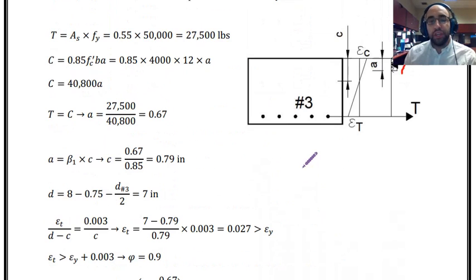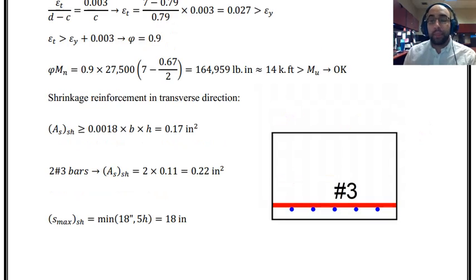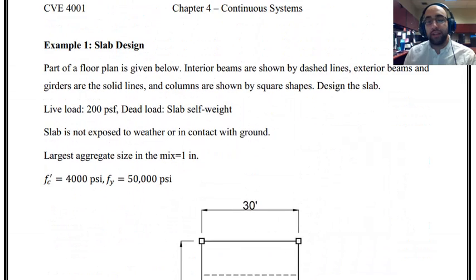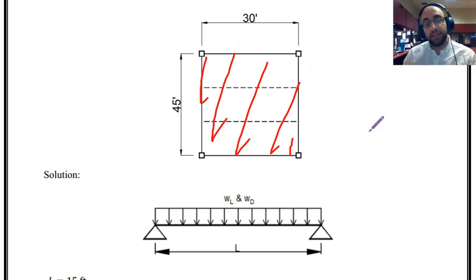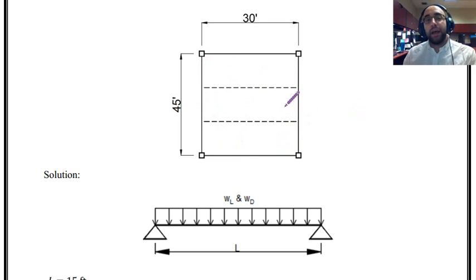If we were looking at the beam, just coming up with the geometry and designing the reinforcement and finding the strength would be all the things that we need to do. Over here, we are designing slabs. And as you remember from the very first chapter, we said one issue that we have for large concrete portions is great amount of shrinkage. Over here, we are designing a very large section like this. This is the slab section, and we have to take care of shrinkage for large sections like this.